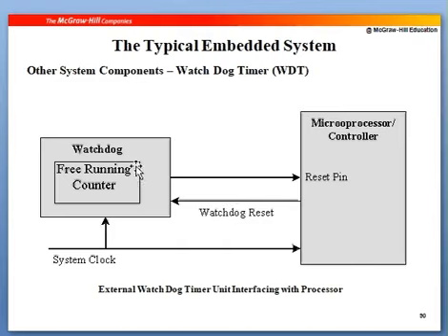Suppose there is a problem and it gets hanged up; then you wait for a while. After 20 seconds, if it still doesn't execute the whole application, there is a problem to deal with. In that case, once the counter reaches 20 seconds, it provides a reset signal to the reset pin of this microprocessor, and the firmware execution application which has been stuck in between will be rerun.